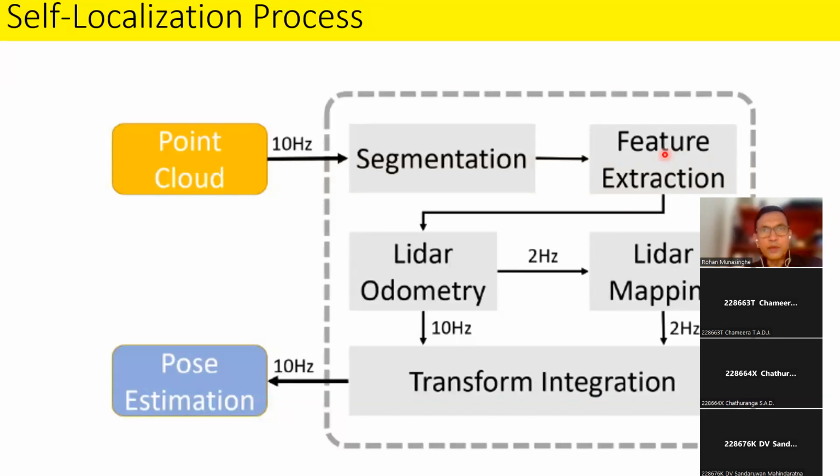What are features? Maybe static features like trees, buildings, and vehicles sometimes are considered as features, because when you first take the robot along that road, whatever stopped vehicles were there are considered as obstacles, because the lidar doesn't know whether it is a car or a piece of rock or a building. It doesn't know that. It just gets the reflection and figures out, okay, it's not traversable. That area is occupied by something. So all of these things are features.